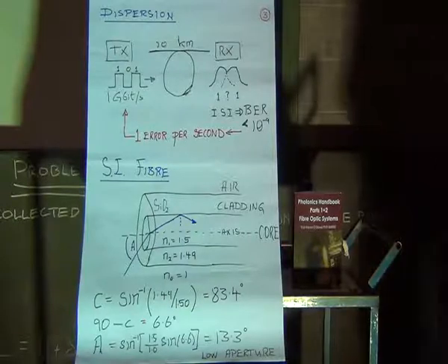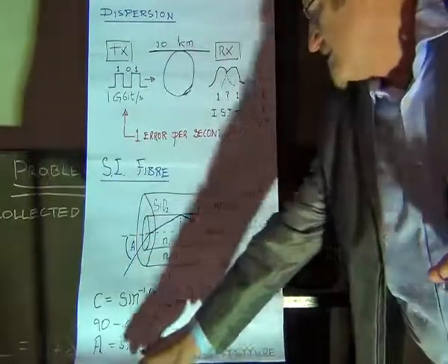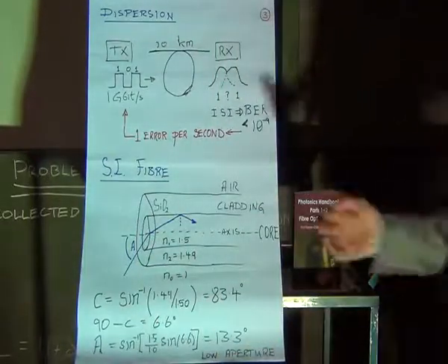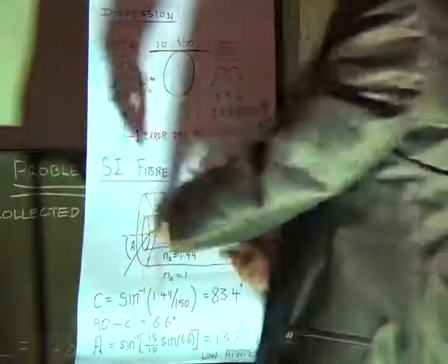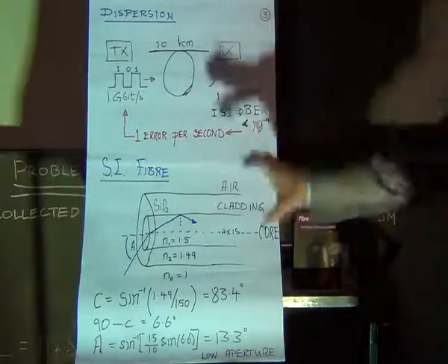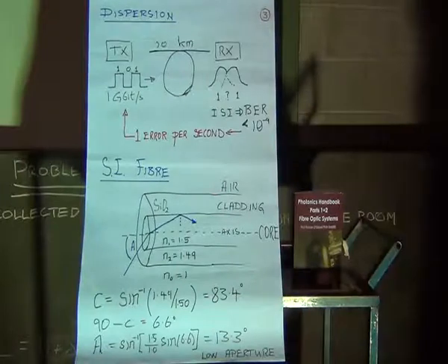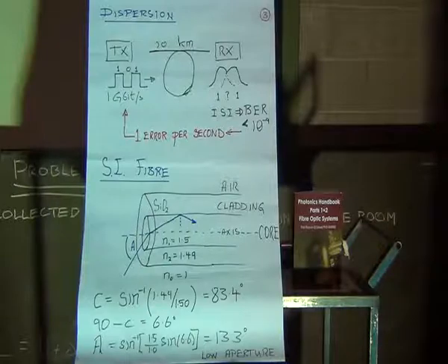All right. Secondly, the angle for A is very small, which means if we want to splice two fibres together, they must be very, very accurately aligned. Or, if we put an optical connector on this, and another one, the connectors must mechanically align with very great precision.